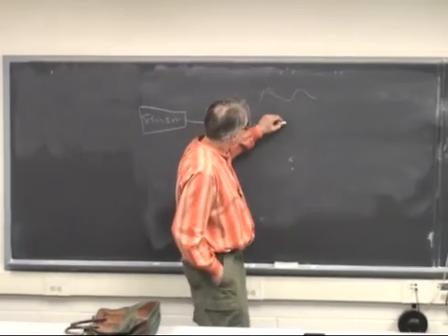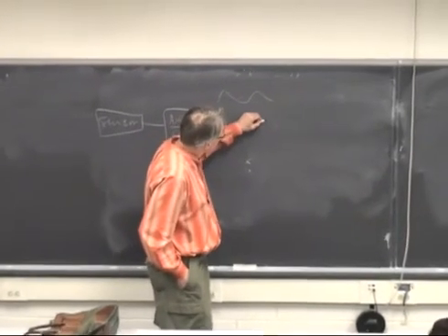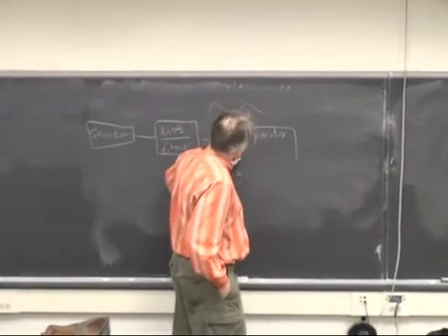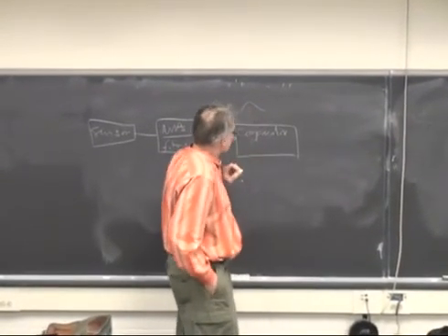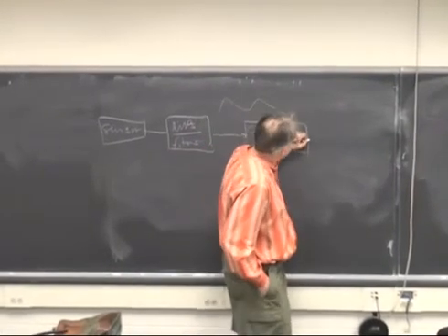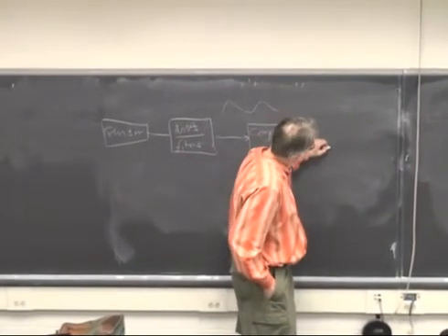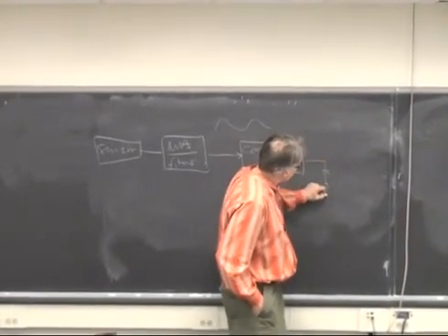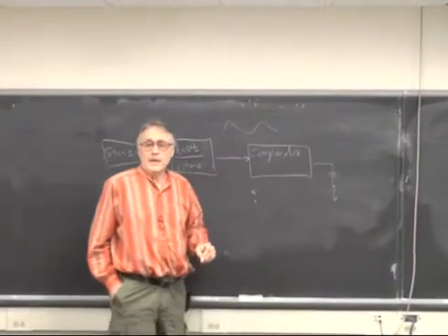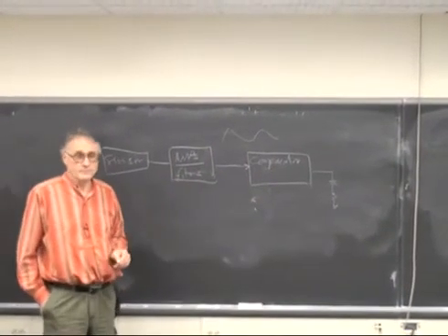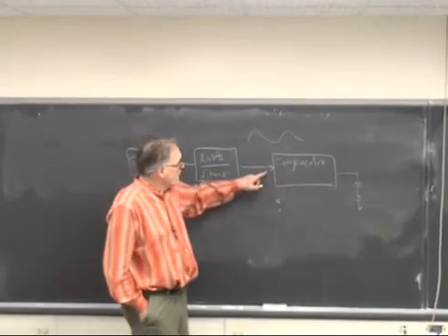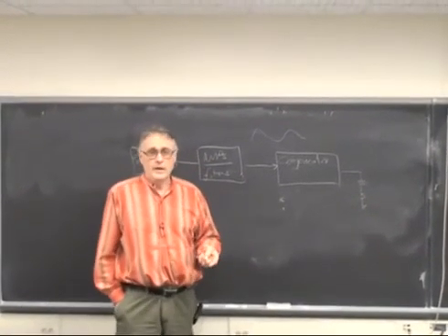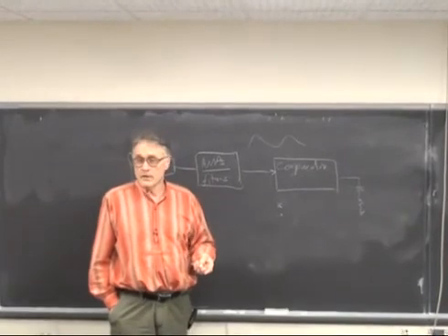So for instance, let's say we put a comparator in here. A comparator, and then an LED to ground. Then you could make a nice little blinky light. It blinks once for every heartbeat. But for a comparator you need two inputs, right? You need a threshold and you need a signal to compare against.